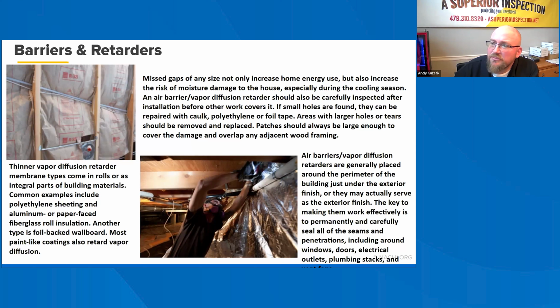Except for extensive remodeling projects, it's difficult to add materials such as sheet plastic as a vapor diffusion retarder to an existing home. Obtaining an energy audit and thoroughly sealing any leaks it reveals is a very effective strategy for slowing moisture movement in and out of the home.